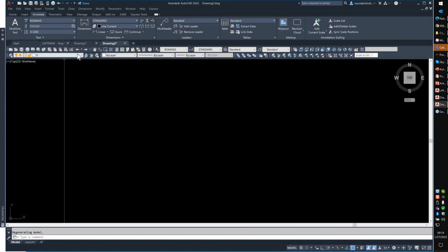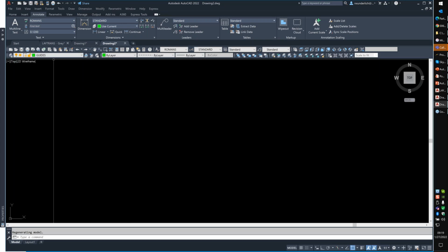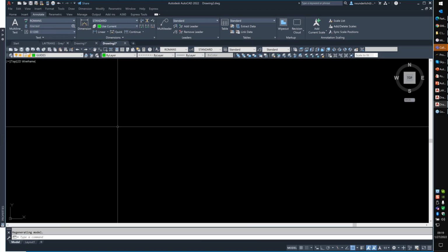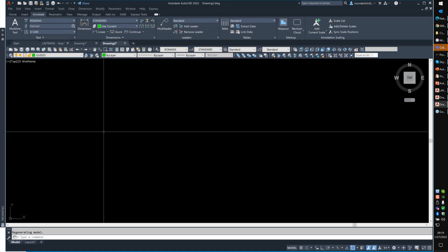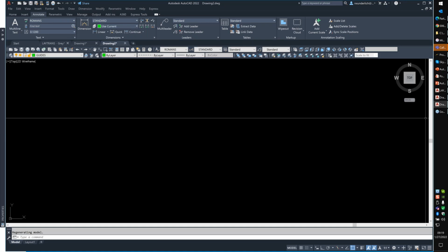Right now in here, I can switch to whatever layer I need. I can start drafting, and I don't need to go in and add my layer. I already have dimension styles. I already have text styles. So none of those things need to be set up on the fly. They're already in my template. Now I know everyone's like, well, we kind of do that. Well, that's important. That's one of the things that's going to help drive your design process and make sure that it is as efficient as possible.